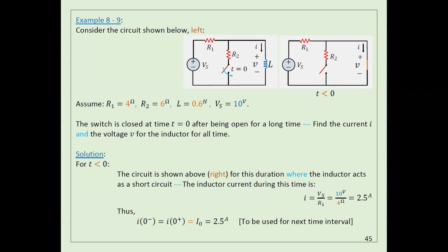Is that okay? Yes. So why would the initial current not be 0? That's a very good question. Why is it not zero? Because it's open. Simply because the inductor was connected in the circuit. The switch was open, but there was a current in the circuit going through the inductor. You understand what I'm saying? Yes, once I open the switch, the current in R2 is zero. That's okay. But still we have current here going through the inductor, which I care about. You got what I'm saying? So again, it's not always zero, it depends on the circuit.